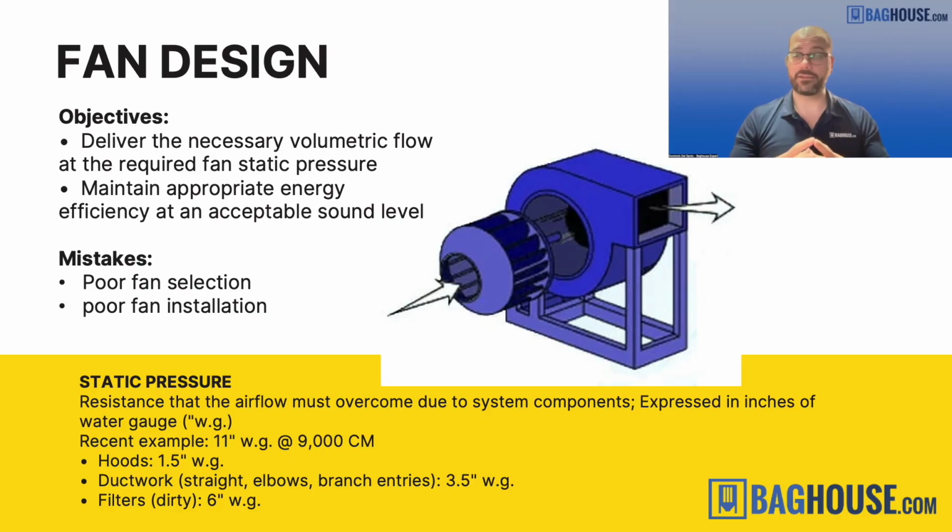Now we take the dust collector and we figure out how much resistance the dust collector at its worst moment will create when it's running. So let's take a pulse jet baghouse, for example. A pulse jet baghouse we usually will run where you will have between 3 and 5 inches of differential pressure or pressure drop. Now, if you want to know more about what that means, you can look up on our website or ask us in the questions later.